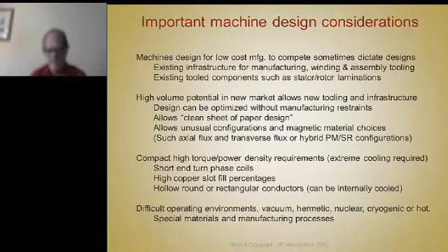Another thing that's important is safety or fault tolerance. That's an issue. A PM machine, if you've got permanent magnets and you get a short in the windings, then you can't turn the back EMF off. You've got a short circuit current that flows, and that can cause a fire and cause death, all kinds of things. So fault tolerance, that's an important issue. Switched reluctance motors seem to have a big advantage for that.